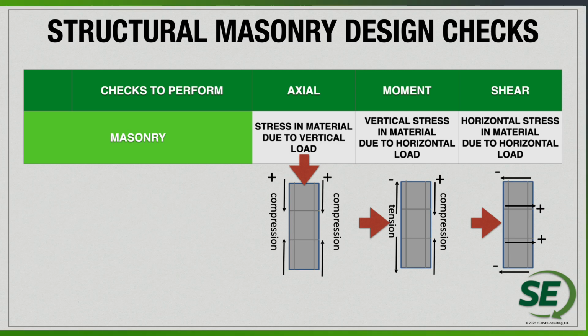We know that for masonry design, we discussed within the different sections that concrete masonry, similar to concrete, likes vertical load. So the more vertical load that we can put in, the more compression stresses that we can create within our masonry elements. Any lateral forces are going to create some tensile and compression coupling forces and shear stresses within our design elements.